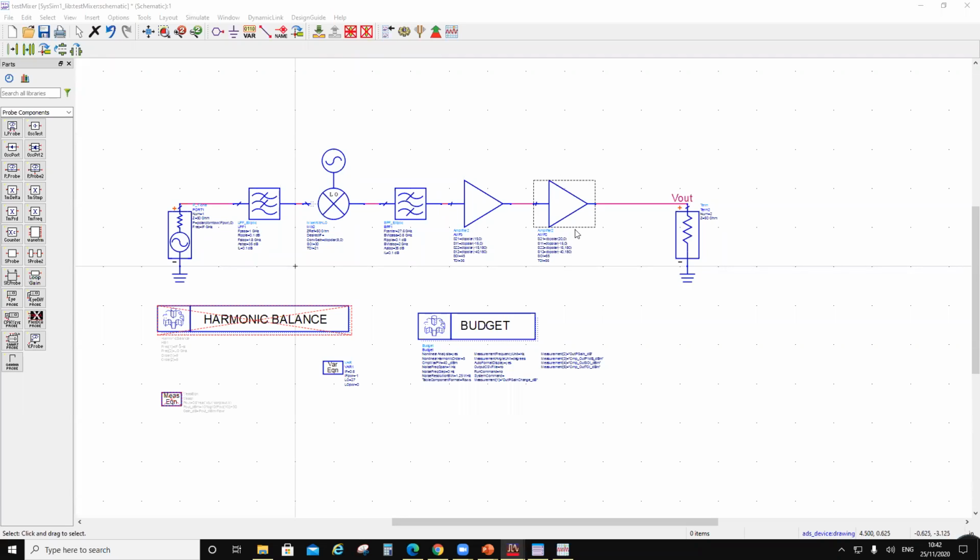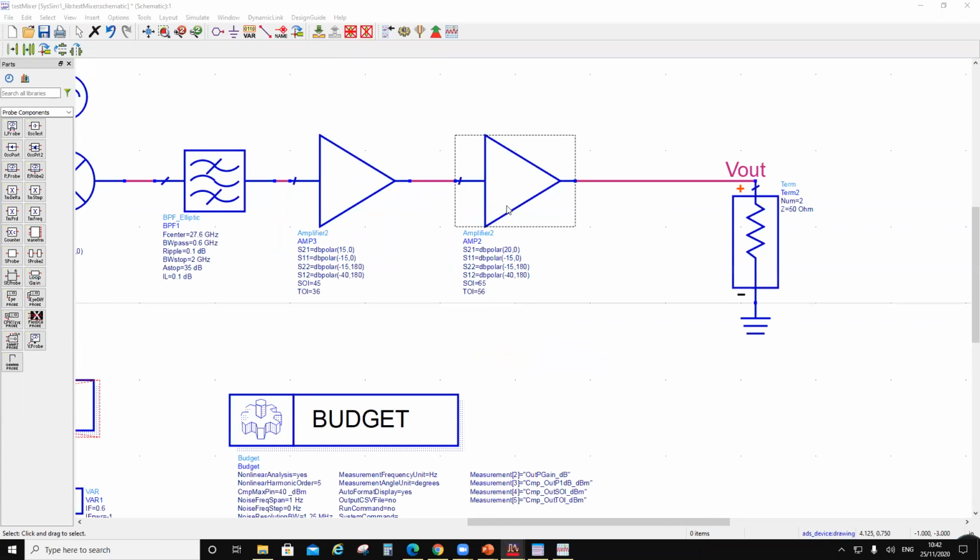So let's say if I want to deliver, how would I modify this chain? Let's say I want to deliver 1 watt. So I should start from here, not from there. If I start from there, that would be like a receiver. If I start from here, that will be like a transmitter. So for a transmitter, I should start with the power delivered. So let's say I want to deliver 1 watt of power. In this case, it will be 42. 1 watt power would be 42, right? And then 1 watt means 30 plus 12, right? Plus 9. So that will be 51.